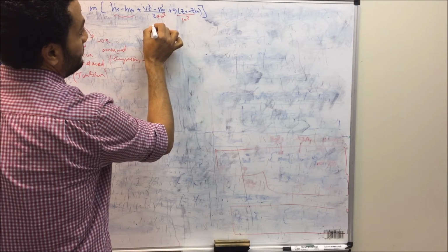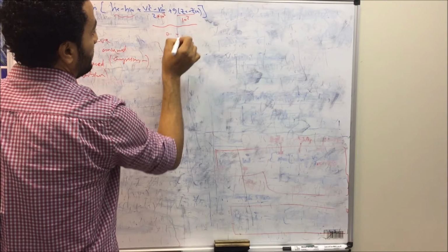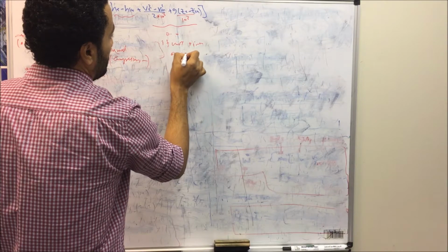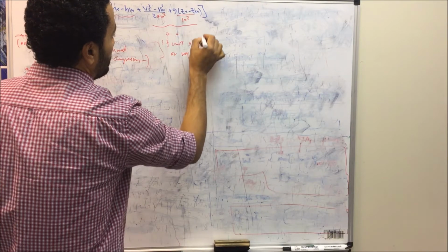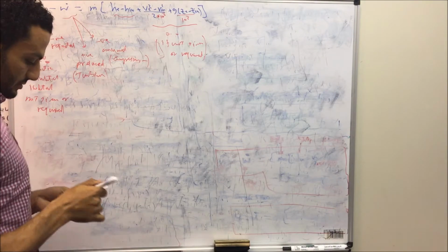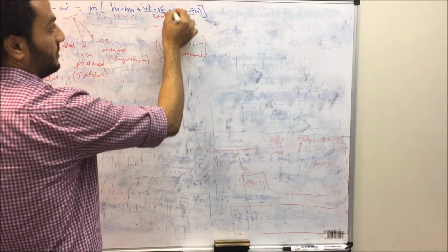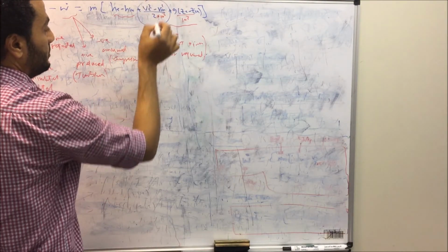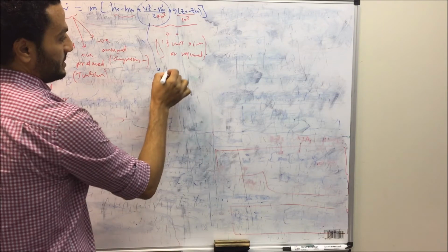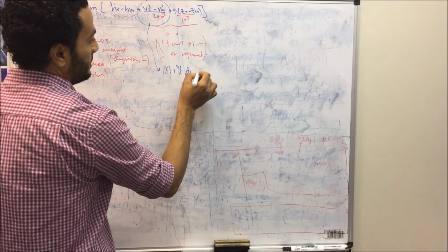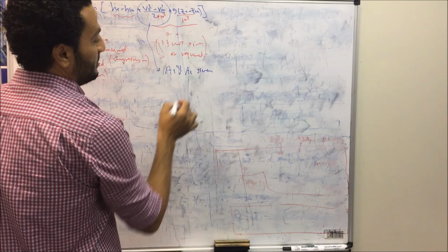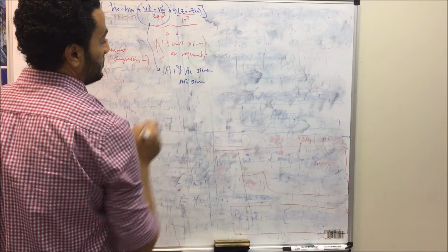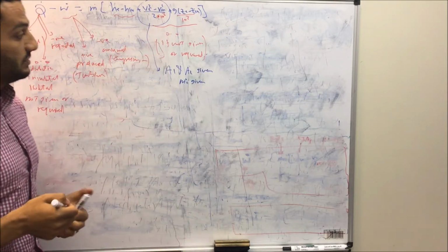Those two terms will be neglected or equal to 0 if not given or required. Usually in most cases the term regarding potential energy will be neglected. But in some cases the areas A1 and A2 may be given, and the mass flow rate m dot is also given. So in this case, can we calculate the velocities V inlet and V exit?